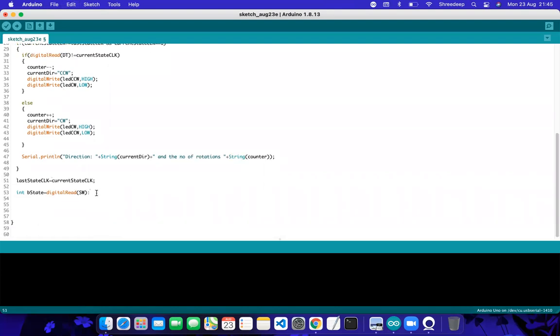Now we are reading the switch statement. If the button state is low, that means you have pressed the button. Now wait at least 50 milliseconds just to avoid the debounce issue. It's a small piece of software, not as hard as what we used in the debounce code. Actually, it's a simple one.